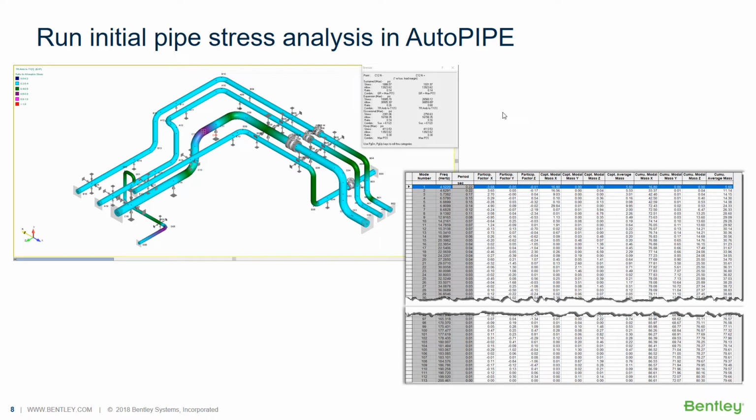They are infinitely rigid supports. Basically, you're saying you're connecting to a slab of concrete at every support. As we go into our STAAD model next, we'll see that that's not the case. We're not connecting to concrete at all. So this is not exactly a very realistic model at this point, but it's a good estimation, especially for a first run through.